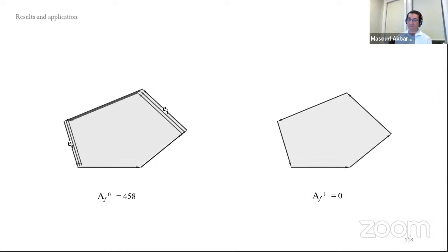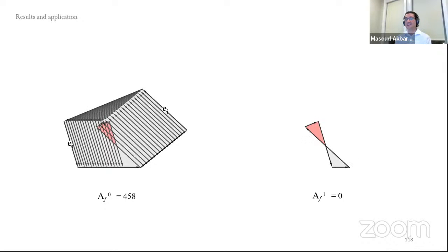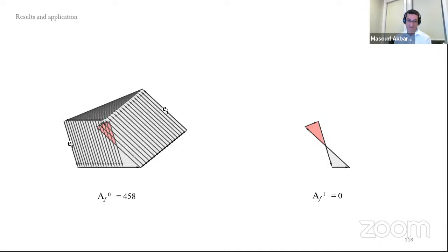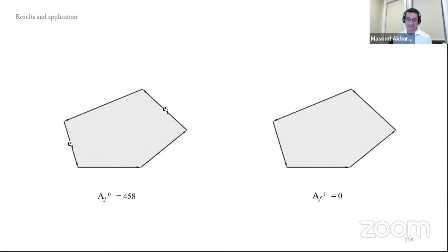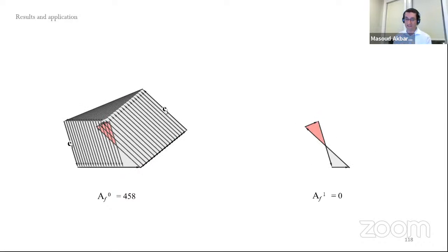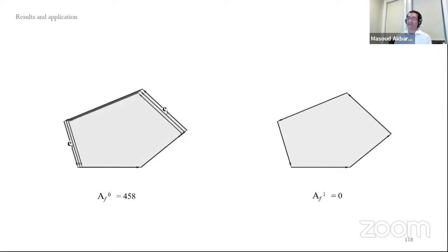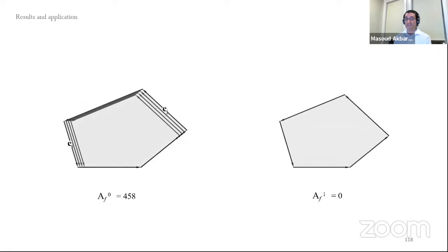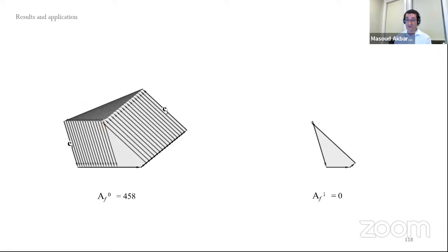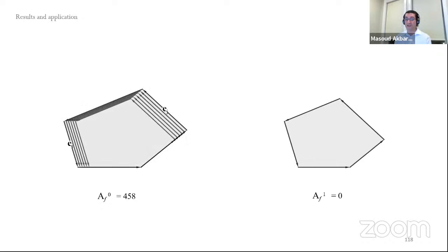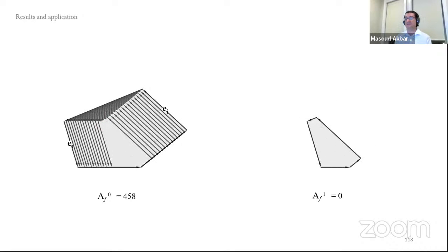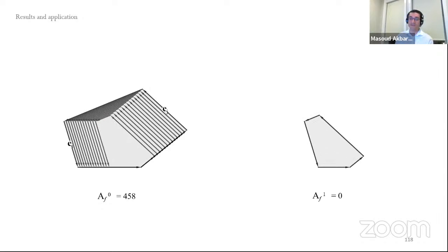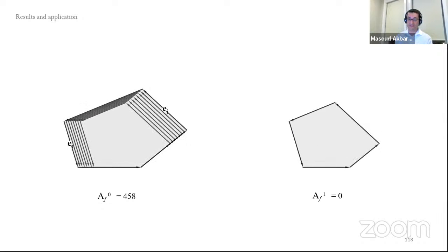And this is quite important because the magnitude of the force in a force diagram is represented by a convex polygon, right? The magnitude of the force in a self-intersecting polygon is represented by the sum of the signed areas, meaning that if your area is flipping as a result of self-intersection, then you have to subtract that amount from the actual amount of the force.